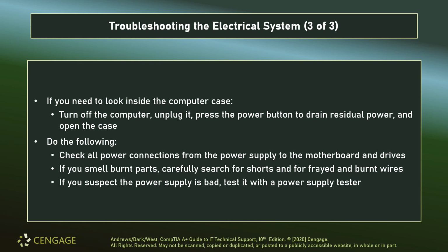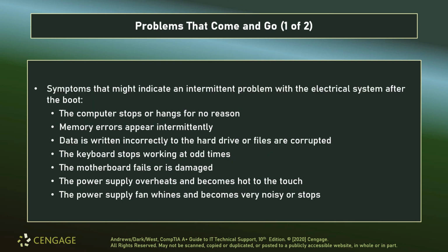If you suspect the power supply is bad, just whip out a power supply tester and give it a quick check. Sometimes what I've run into is that the power supply is perfectly fine, but when I check one of the connectors for the SATA cables, specifically the one going to the operating system hard drive, that connector has gone bad or has cooked in some capacity.